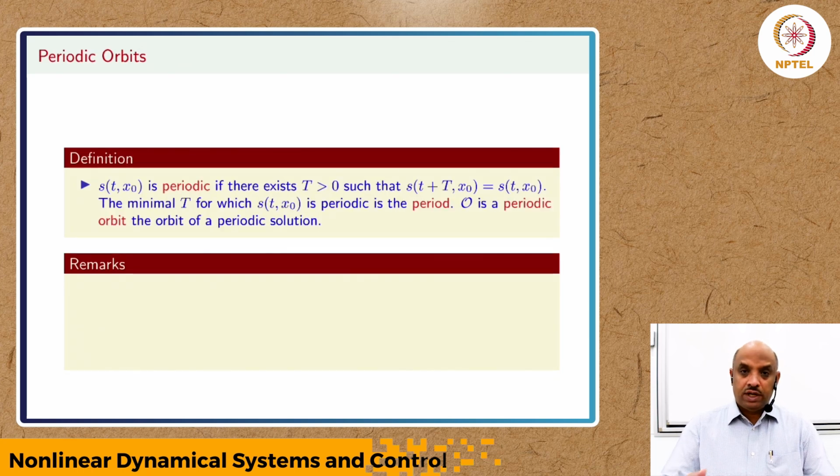So then, where are we going with this, right? Many times we may end up with the asymptotic behavior, the positive limit set, being just the equilibrium point, which is most of the time in the controls case what we want. We want to make sure that the omega limit set of a dynamic behavior ends up with a single equilibrium point. In some cases, we may end up with some kind of periodic nature or a limit cycle that we will define in a second.